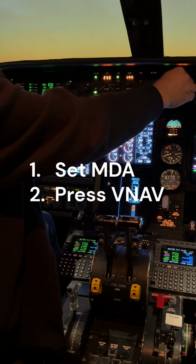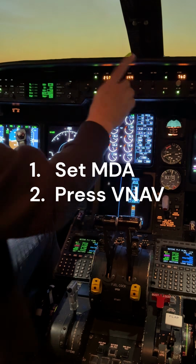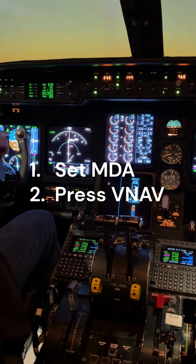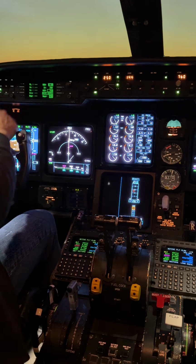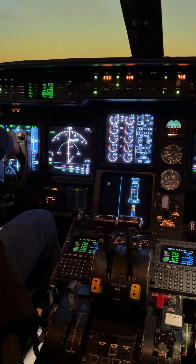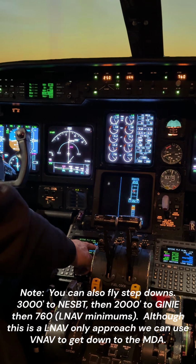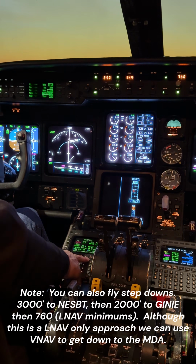Now, if you were doing an LNAV VNAV, you'd set field elevation here, but we're not. We're doing an LNAV only, so we're setting the MDA of 760. So we set the minimum, we pressed VNAV. When we press VNAV, what do we got? We got VALT, so we're holding altitude with VNAV engaged. And you see a 3,000 in blue. 3,000 in blue is exactly where we need to be because item is 3,000 feet, Nesbitt is 3,000 feet. The FMS says Ginny's at 2,000, and then our minimum of 760.